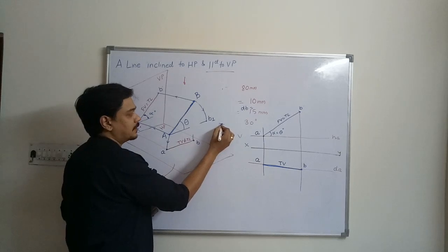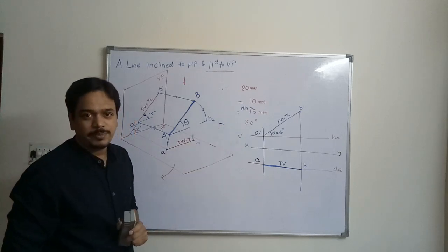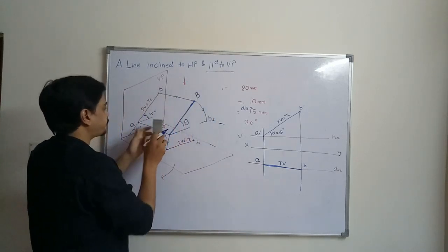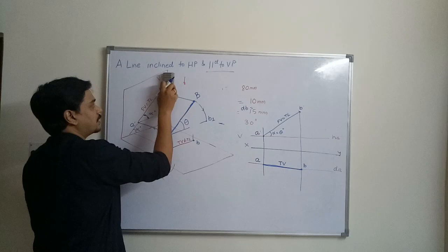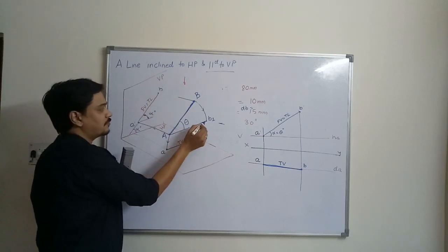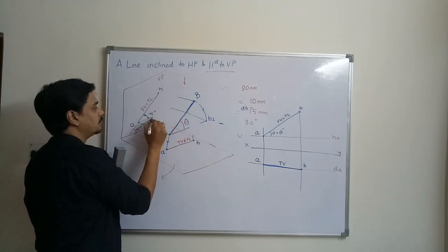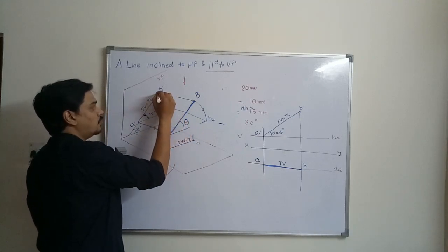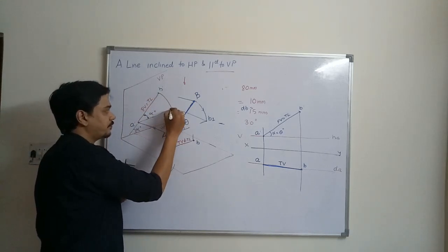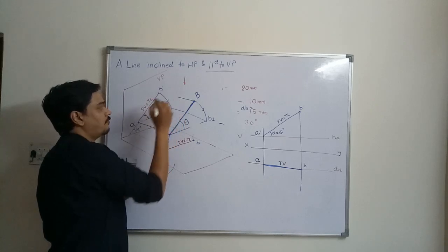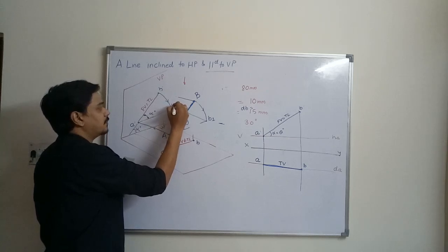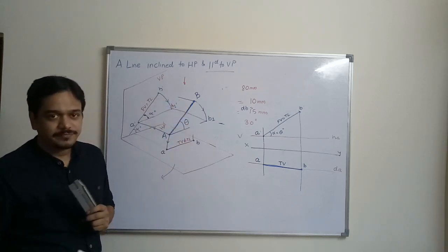If you obtain the projection of point B1 on the front plane, how will it be seen? This will be projected as it is over here. As a result, you will get the same point over here as a rotation of the front view. So now this point is nothing but the point B1 dash.